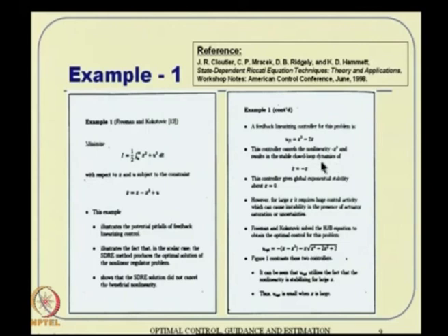That is what is done. So, this is your feedback linearizing controller, which is x cube minus 2x, and then it operates like this. You can also argue that this does the job, because it also takes x to 0 anyway. That is what the asymptotic stability solution means. So, this kind of solution is probably too complex and not needed. But we will quickly see that there are some nice properties of this compared to the feedback linearizing controller.